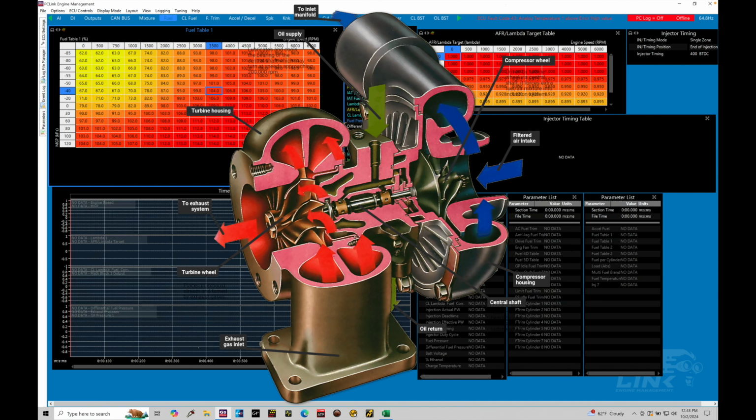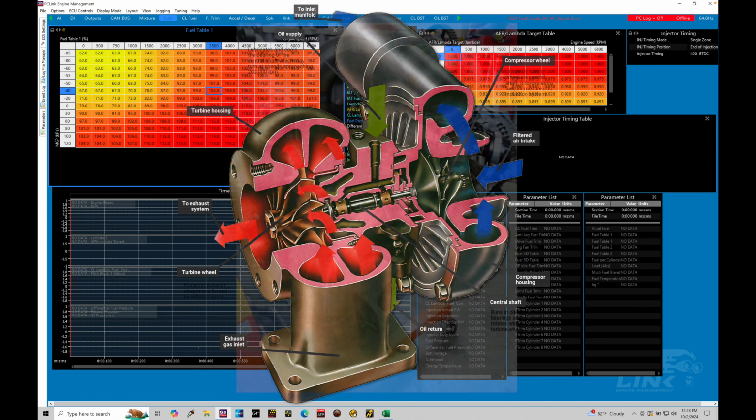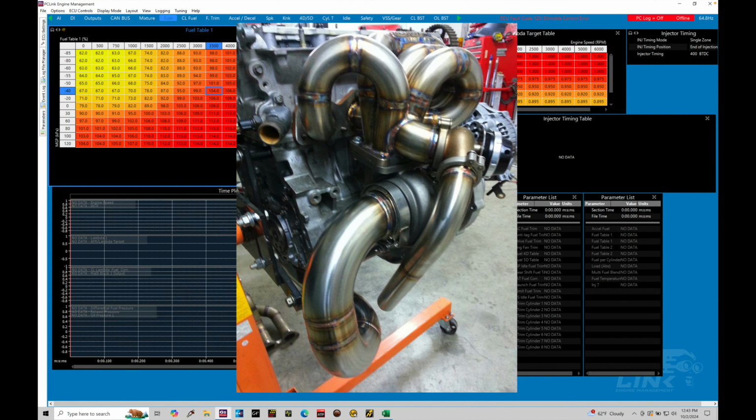Now, going and taking a look here at a typical aftermarket turbo setup, we're going to find we have a couple different components here. So we have a turbo manifold, exhaust manifold, that's going to connect the exhaust ports to the turbine housing. Then we have our actual turbocharger. In this particular picture, we find we have a downpipe that's connected to the turbine housing. So any of the exhaust gas, as it's spun the turbine wheel, it's going to discharge to the turbine housing, go through the downpipe, and then go through the exhaust and be expelled out into the atmosphere.